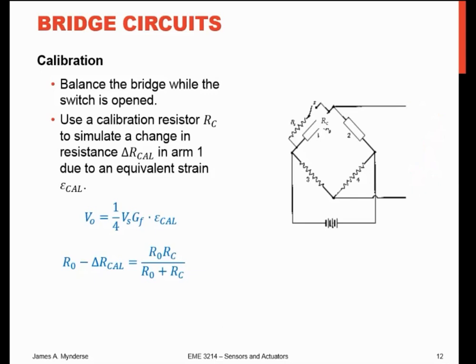Most likely what I'll do is I'm running out of room. Let me move this over here. Put a resistor there, put that into an op-amp circuit. But the gain and those resistors aren't going to be exactly what I think they're going to be. So we've got to do something to calibrate this bridge from end to end.